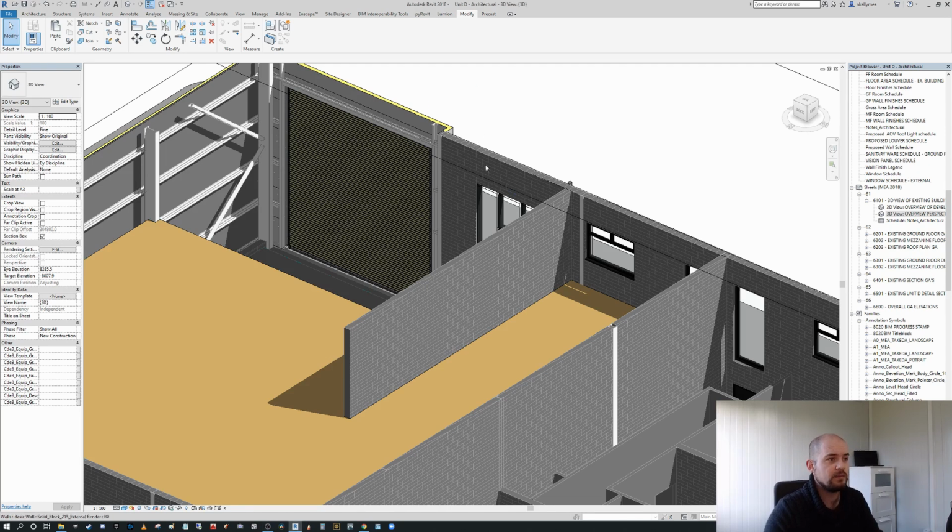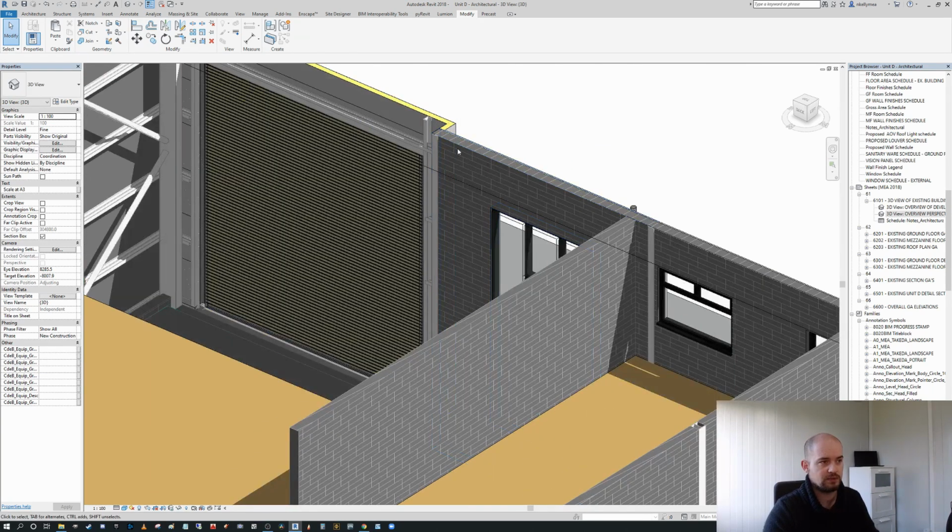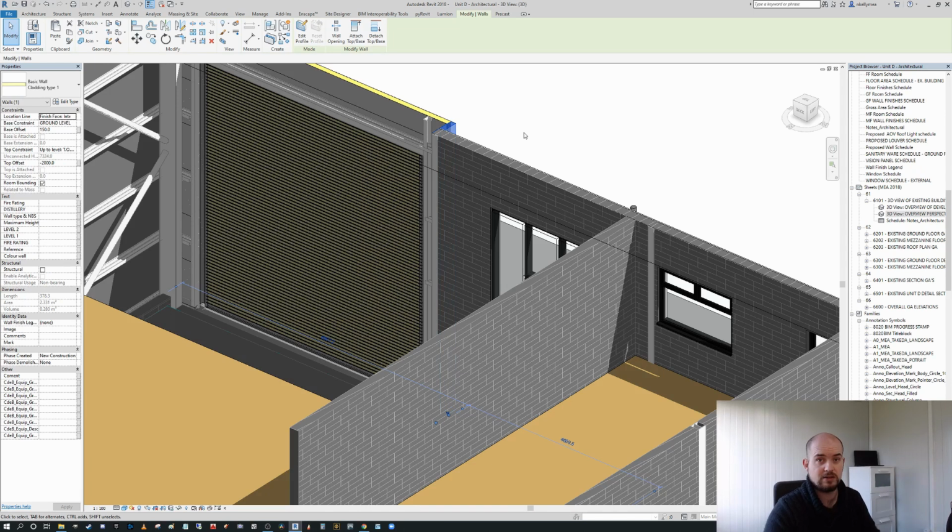Looking at this blockwork wall here, let's just say that we actually have layers of information in behind this blockwork wall. Let's say I want to select the return wall here, but I don't have access to the top of the view like that. What we can do is highlight the element in front, and again, using the tab button, we can cycle through until we get the single selection of the element that's behind the primary element in the view. So in this instance, I'm selecting the cladding that is behind the blockwork wall, and then I can click and I have my selection. So it's that simple.